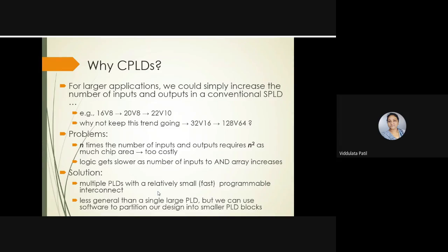If we use a number of PLDs, the inputs required for each PLD will be less, and then we can program these PLDs in such a way that whatever your application is, it can be implemented. It is less general than a single-design PLD, but we can use software to partition our design into smaller PLD blocks. So whatever your application is, you can partition it into simple blocks and then design that particular application. That is a CPLD.